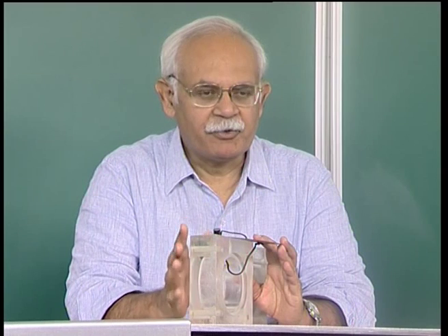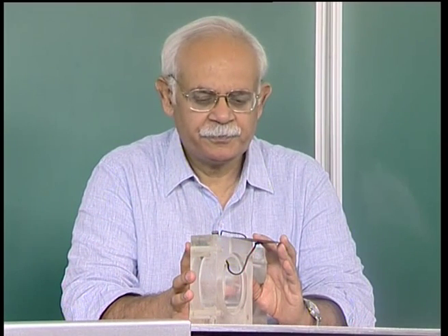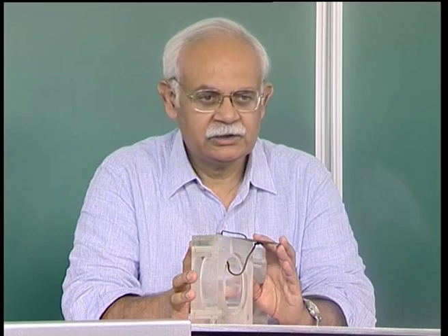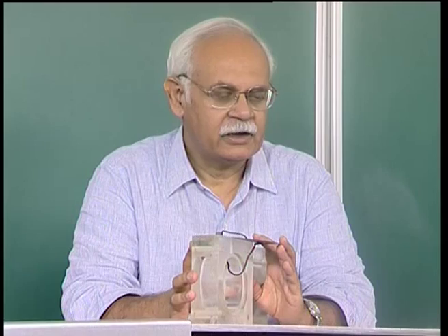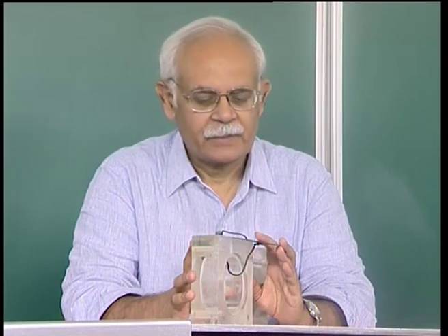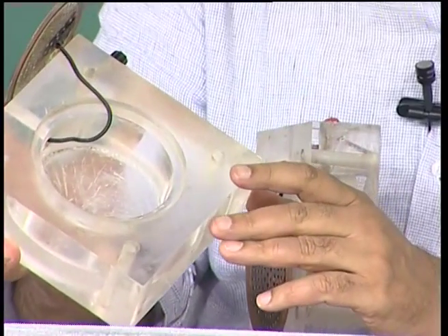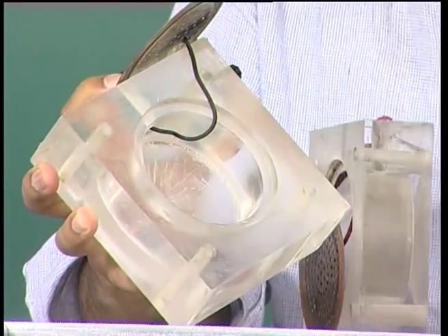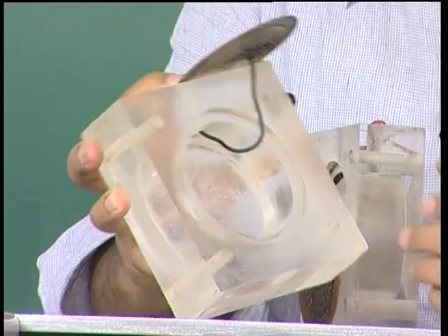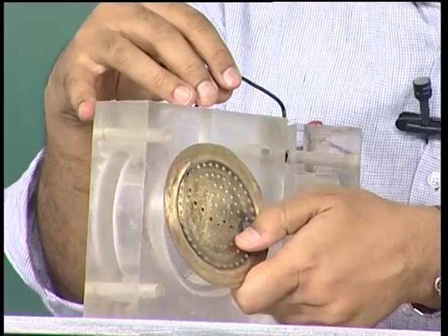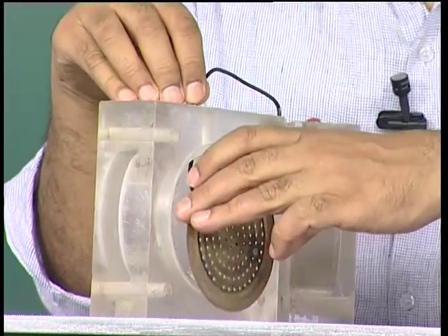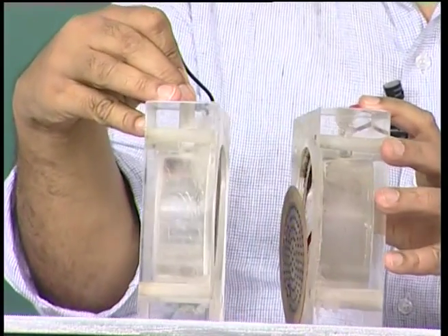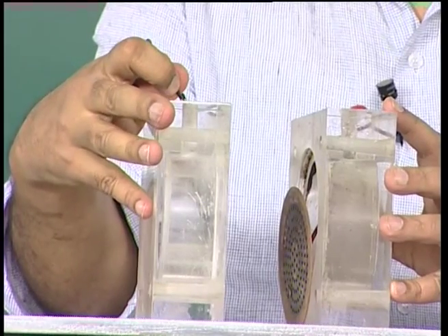Thank you. Before we close the discussion, let me show you a diffusion cell kind of a setup, which can obviously be modified to carry out a test in accordance with ASTM C1202 or AASHTO 277. This is one of the cells or one of the reservoirs with a hollow space here, which can be filled with either sodium hydroxide or water or a chloride solution. This is a wire mesh which is used to apply current if the concrete is being placed in between the two reservoirs like this. So, we have two reservoirs on either side of concrete.